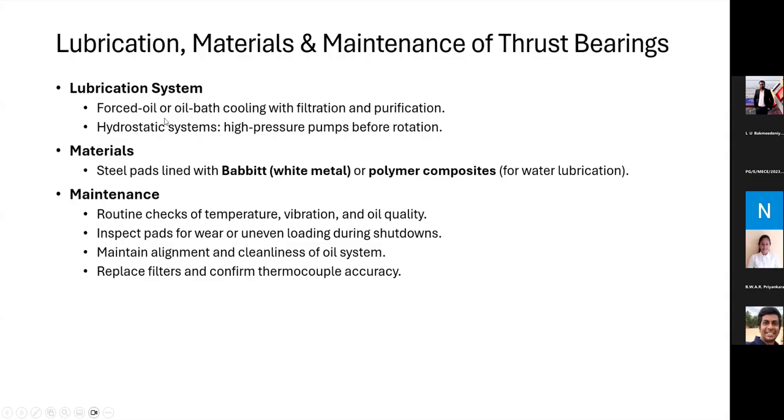So the lubrication system is forced oil or oil bath cooling, and then you can look at them. So maintenance-wise, routine checks of temperature, vibration, and oil quality, inspecting pads for wear and uneven loads, maintaining alignment and cleanliness of oil systems, and replacing filters and confirming thermocouple accuracy. These thermocouples are installed inside the bearings to monitor the temperature. And if the thermocouple accuracy is lost after a long time, an incorrect prediction of the bearing performance will be made.